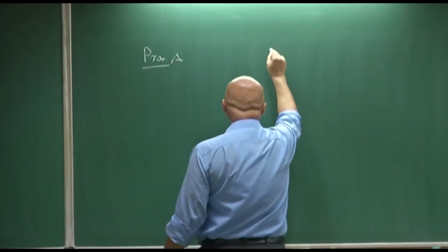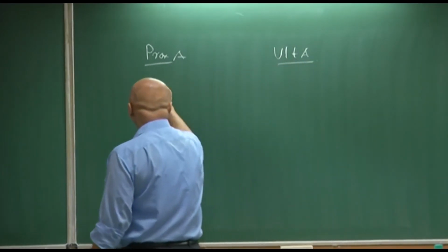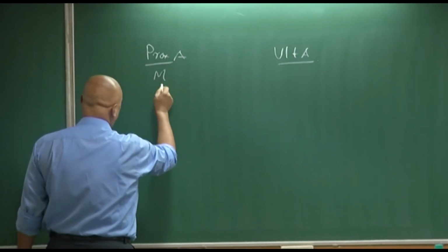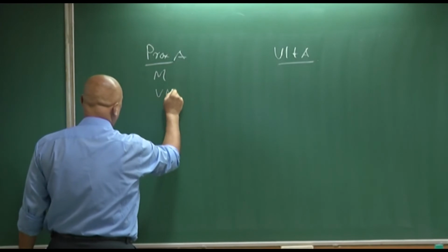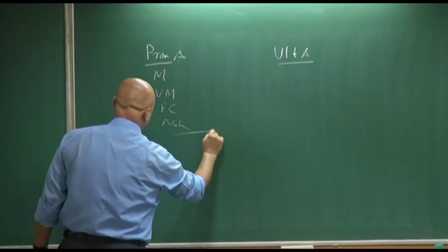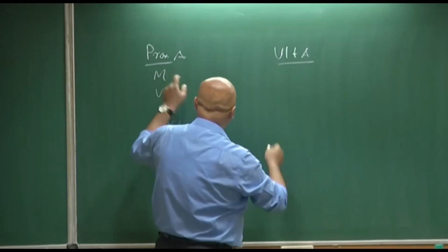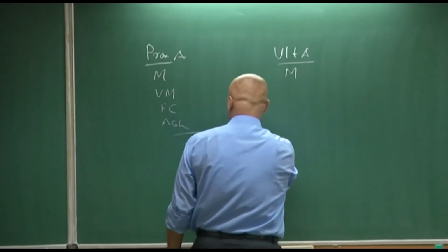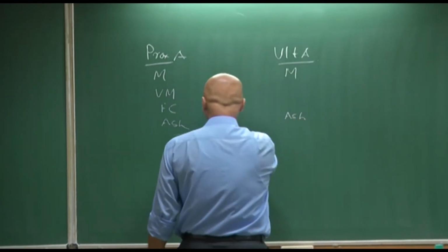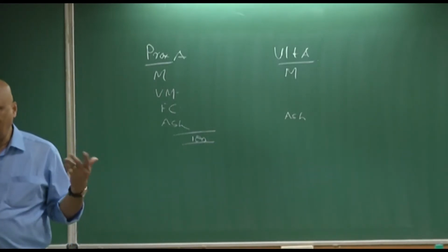This is proximate analysis and ultimate analysis. Here, the coal is classified by moisture, volatile matter, fixed carbon, and ash. The total should give you 100. Moisture stays as moisture, ash stays as ash, exactly. The volatile matter and the fixed carbon are supposed to be carbon, solid carbon.